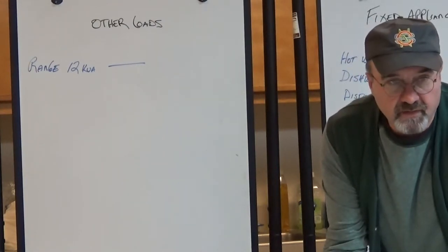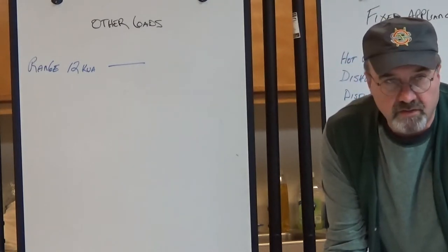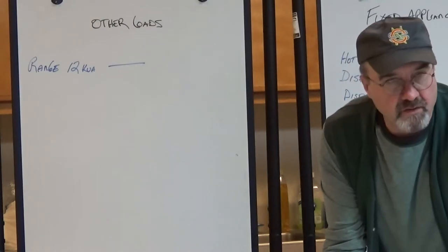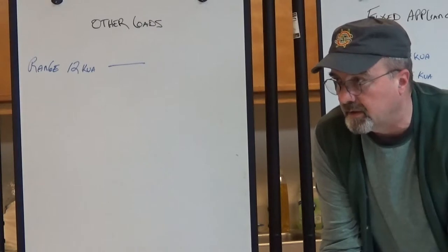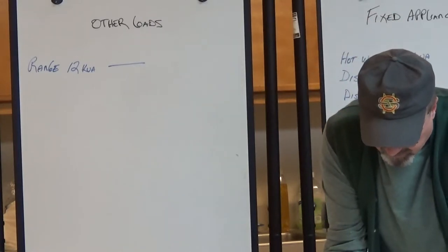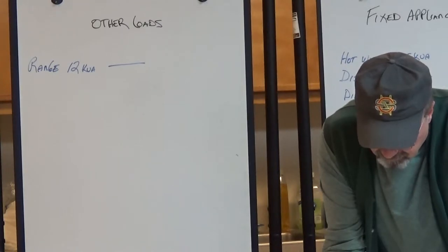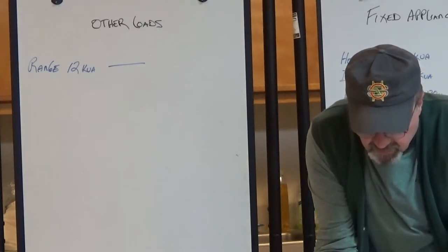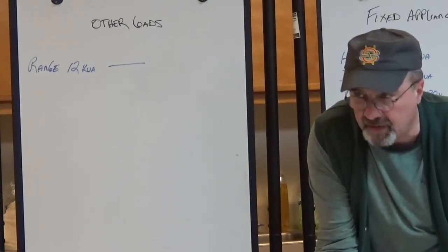So on a stove, you have resistive heating elements, which is really, you know, power is measured in watts. The code is saying here that we're going to consider kVA and watts the same way. And so if we go over to the next page, turn your page.